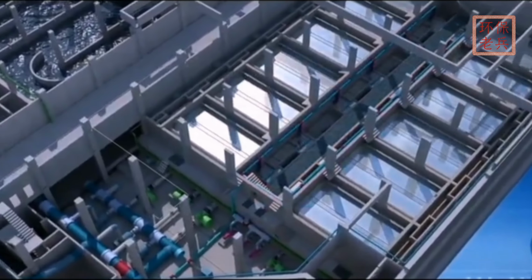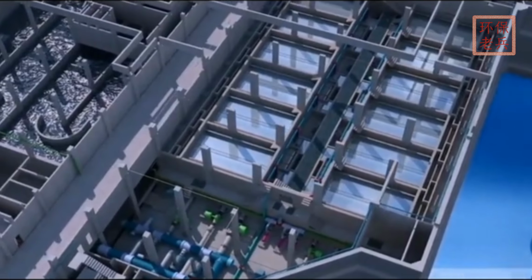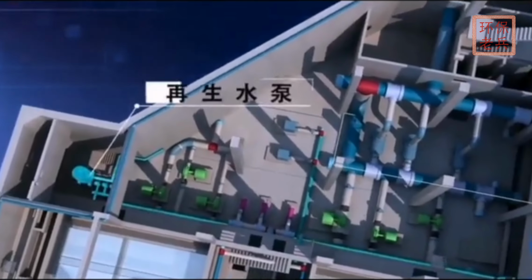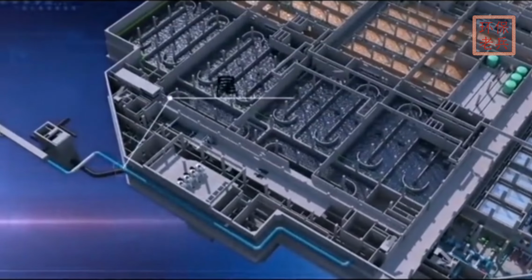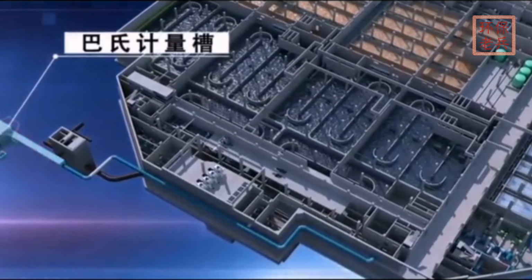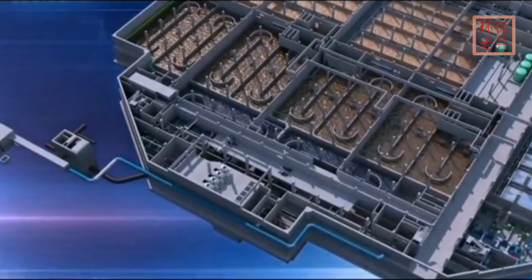1. As backwash water for the V-type filter. 2. To discharge via reclaimed water pumps for washing, landscaping, groundwater recharge, etc. And 3. Sent through tailwater pumps to an ultraviolet disinfection system. After flow measurement through a Parshall flume, the final effluent meets discharge standards and is released.